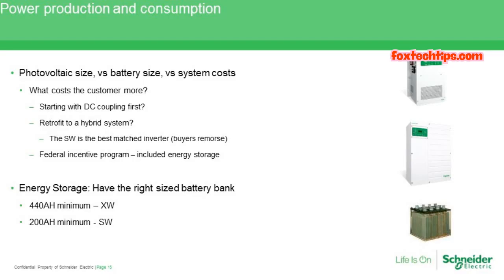So some of the calculations that we've shown so far could be a surprise to some installers or people who aren't initiated into grid tie or grid tie with battery backup. And it's just the nature of the course when working with these systems that the typical efficiencies are well within the standard parameters of just about any other system. But from panels to battery efficiency to inverter efficiency, they just start to add up along with wiring.